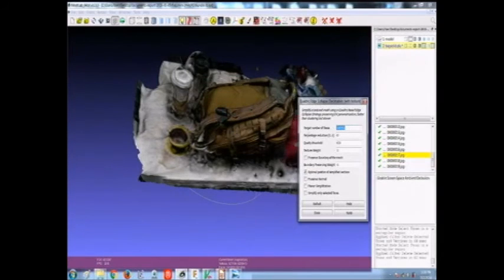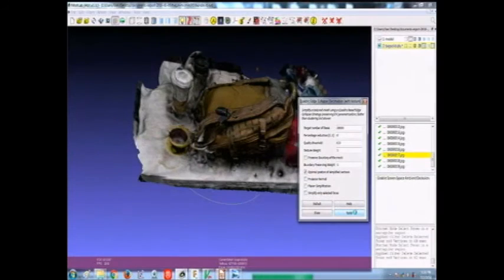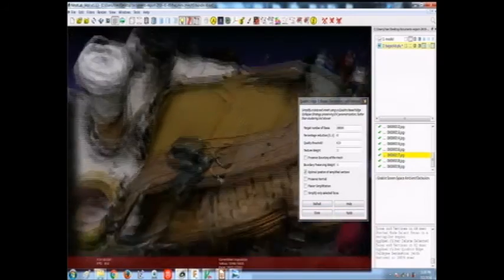So let's go ahead and reduce this down to 20,000 polygons right there. Bam. We'll hit apply and see if anything shifts on the screen. You might see a little bit move around, but it will be hardly detectable. Anybody see anything, right? Just a little tiny blip. You can still zoom in. You can still see the surfaces.